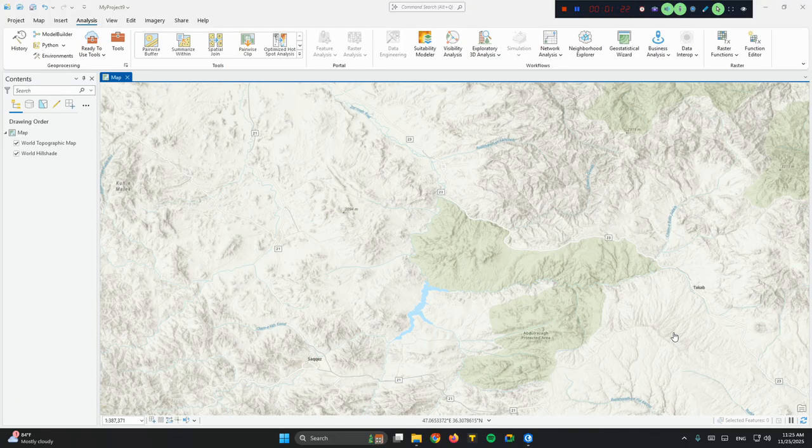We have to have the elevation data in order to delineate our watershed. Before that, we need to download our data. There are various sources and platforms where we can download our DEM data. We can download it from the USGS dataset, SRTM or Shuttle Radar Topography Mission, the ASTER dataset from NASA Earthdata, ALOS, Copernicus, MERIT, and OpenTopography, each of which has various spatial resolutions, depending on your purpose.